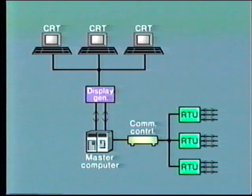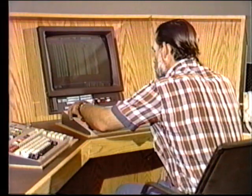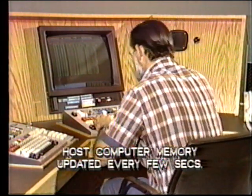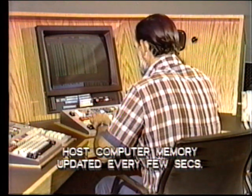The heart of the operator interface is the display computer or display executive, which controls the operation of all of these programs. Let's look at this in block diagram form. The display computer is connected to the host computer or CPU, and from here it receives information which is then made available for display on the CRT. As we already mentioned, the particular display required is requested by the operator at his workstation keyboard. Remember that the host computer memory is being continuously updated every few seconds from the RTUs. And it's this continuous update that appears on the display screen.